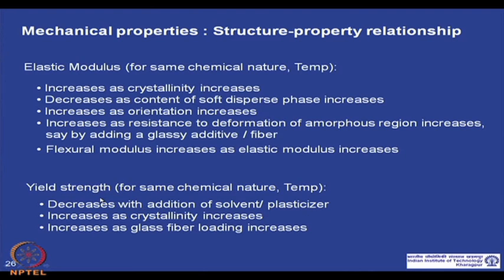Yield strength is the stress where yielding starts or permanent deformation starts. With yield strength, if we add some plasticizer or a solvent molecule, obviously the yield stress comes down. It increases just like modulus, it increases with crystallinity of a semi-crystalline polymer, and if you add glassy additives like glass fiber, then yield strength increases.